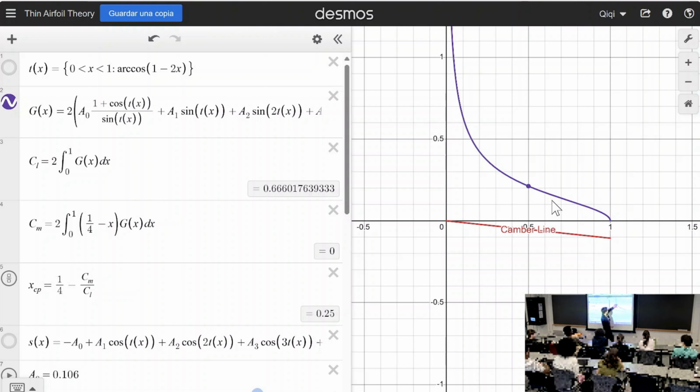If you load the weights on the flat plate according to this, the left side, right? By how much? Well, you need math to do that, and if you do the math, you'll find it is exactly 1/4. So the fact that this function has a center of weight equal to 1/4 is actually the reason the quarter chord is so important in aerodynamics.